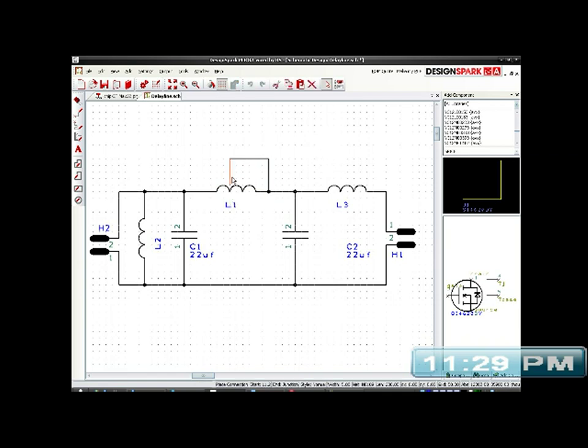So, imagine that was a wiper on a pot. Same principle, except it's a tap, or it could be a wiper even if you've got a coil on a bobbin. The old TVs years ago used to have carbon wire with a slider that you would slide along. Or even coils can be done like that, just the same principle really. You could use a copper wire coil instead of carbon wire, with a tap point to move the tap in, to adjust it so it becomes a variable inductor instead of a variable resistor.